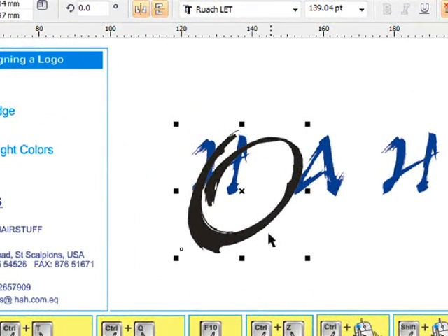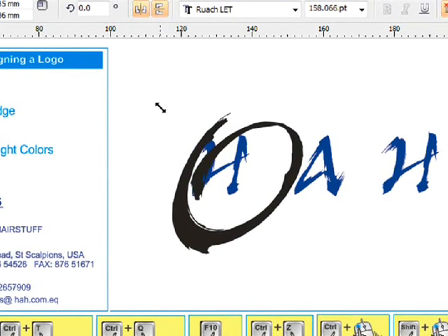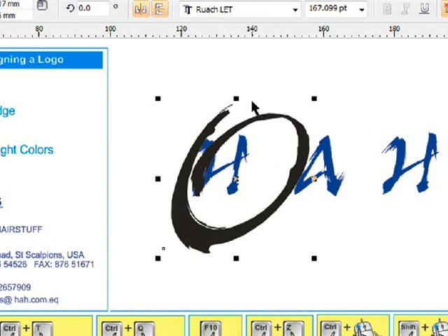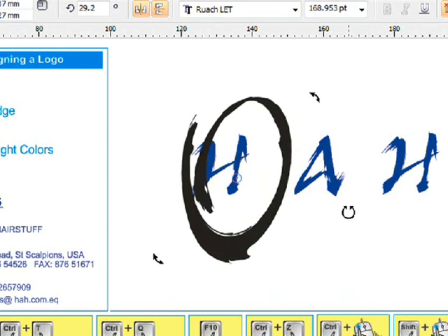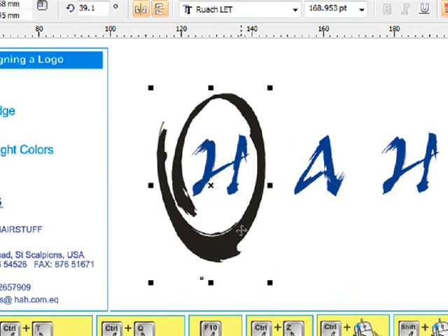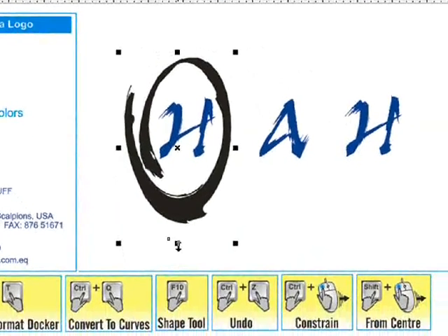You'll notice that I'm resizing by pulling on the black corner handle of this object. Whenever you select an object the first time, you can see the scale handles or sizing handles in the middle there. If you click a second time, you bring up the rotation handles. Now I'm going to use the rotation handle, and in the middle there on those side handles, they're what we call skew handles. Just pop that there. I'm going to squash it up a little.